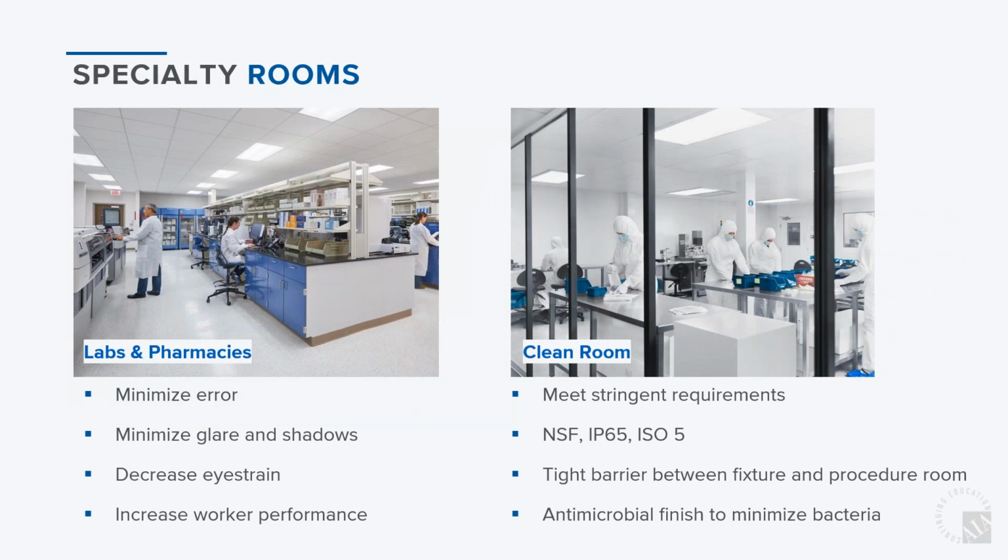So this is kind of a continuation. You have these specialty rooms. Just like the one before, there are going to be certain rooms, maybe labs or pharmacies within hospital settings, that require maybe clean room. Your clean room rated fixtures are going to carry a lot of certifications. They're certified NSF, which is the National Sanitation Foundation. They're going to carry IP65, ingress protection, and ISO 5, which is International Organization for Standardization. These requirements just ensure that contaminated particles do not enter the room from the plenum space.